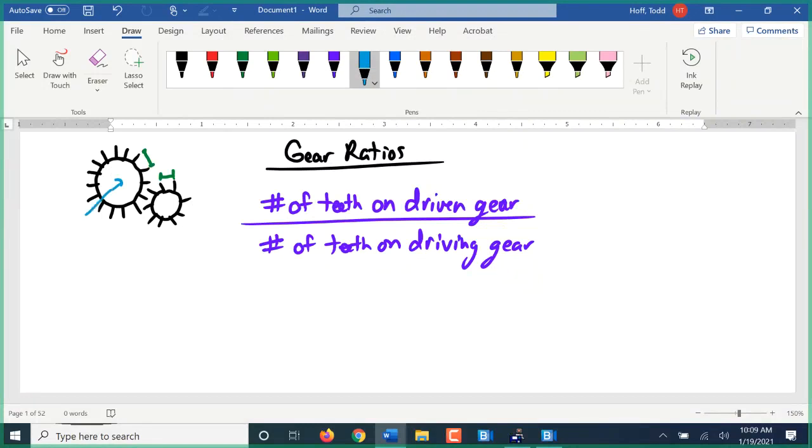This might require a little bit more stretch of the imagination. And that looks like a shaft with a small electric motor on it. That large gear now, if we were to separate the two gears, that large gear would keep turning. It is the driving gear. If I count the number of teeth, it has 15 teeth. The small gear has 9 teeth.